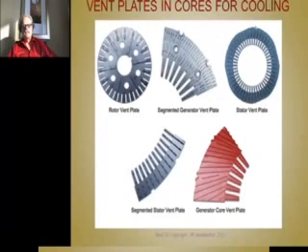Here's a stator vent plate. Here's another segmented stator plate, and here's a generator vent plate. Obviously, this one only goes one direction of rotation, and there's some pumping action here. But this is a stator core. I'm not sure why they're angled like that. But what these consist of is a fairly thin piece of steel with stand-ups on it.